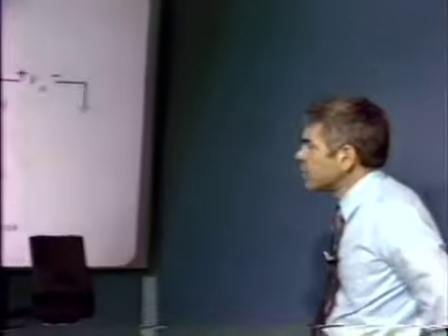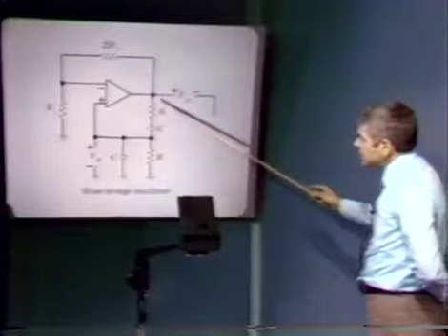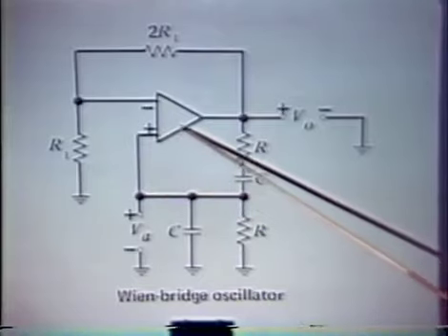The typically very high purity oscillators use other techniques and are really attempts to make a system that looks very much like a linear feedback system with a complex conjugate pair of poles on the imaginary axis. One of the popular topologies is the Wienbridge oscillator, and I show that here. There is the bridge network that, at least in this implementation, consists of a series and a parallel branch using equal RC values. And then again, in this implementation, we have an operational amplifier.